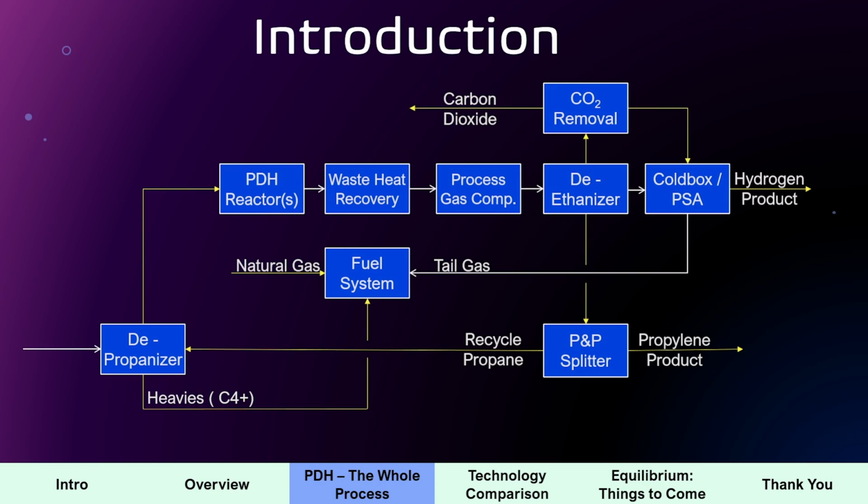So if I'm talking about something like methane and butane, you would look at the boiling point of each of these components, and you're going to find that methane is way more volatile than butane. And the bigger the distance between those boiling points, the more compact the number of trays I'm going to need in order to separate them.